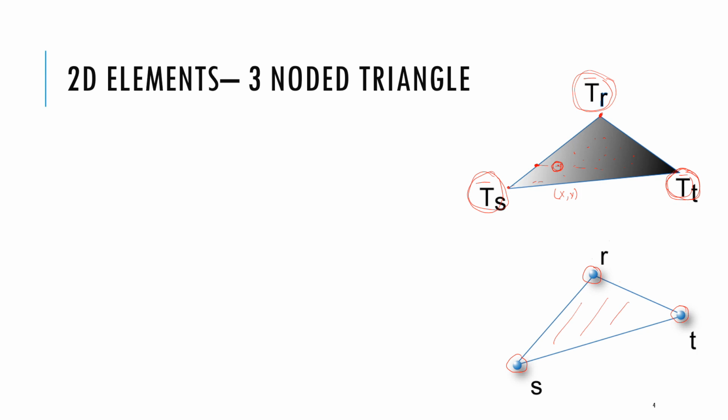Now, what I just described can also be algebraically written this way. So let's say I want temperature in general for a location xy is given by some alpha 1 plus alpha 2 x plus alpha 3 y, where alpha 1, alpha 2, alpha 3 are unknown, but T is this kind of a linear function of x and y, as I was just showing by interpolation.